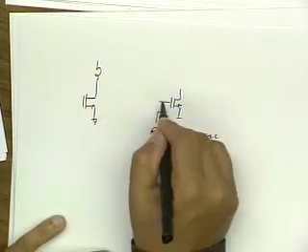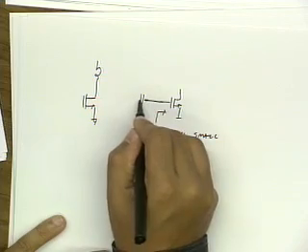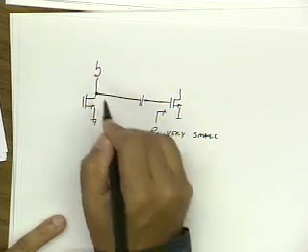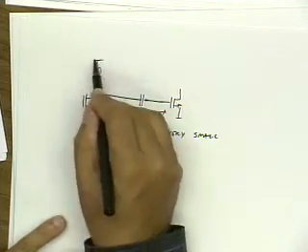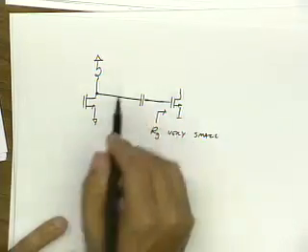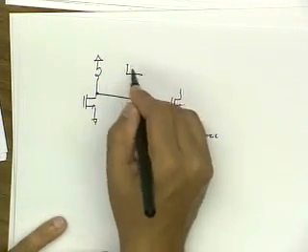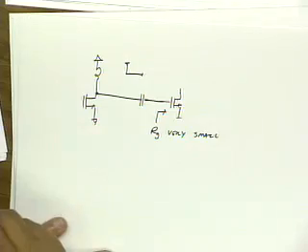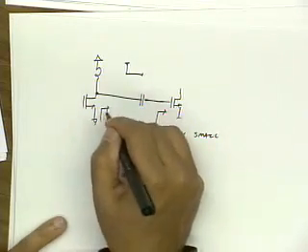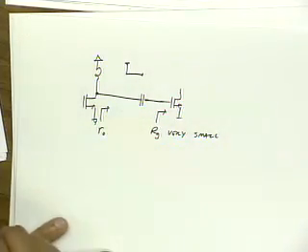To do that, I connect a capacitance in series and an inductance to ground. So this is my L matching network. And now, looking out here, I should see RO for an impedance match between these two stages.